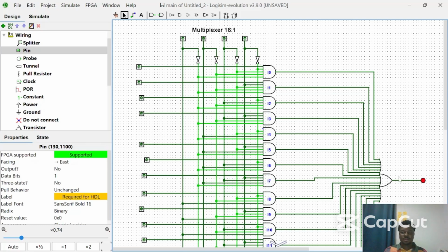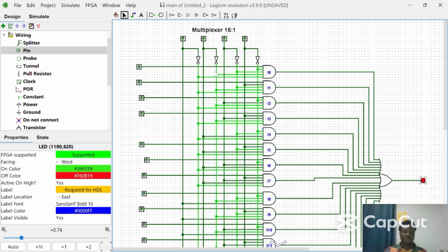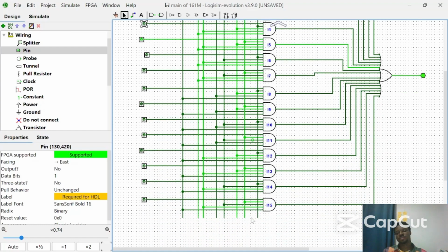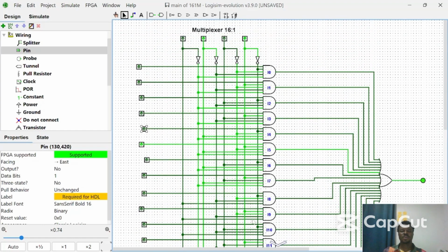The LED is red, that means it's off. So this is our 16 by 1 multiplexer, and you can try it. It's 0000 on our stimulator. I0 selects 4 zeros, all are zeros. Turn on the stimulator here and it is green. Let's try I5 where we have 0101. So 0101 and I5. I5 is green. We can try it for all the others and it will work. So that is it for our 16 by 1 multiplexer.